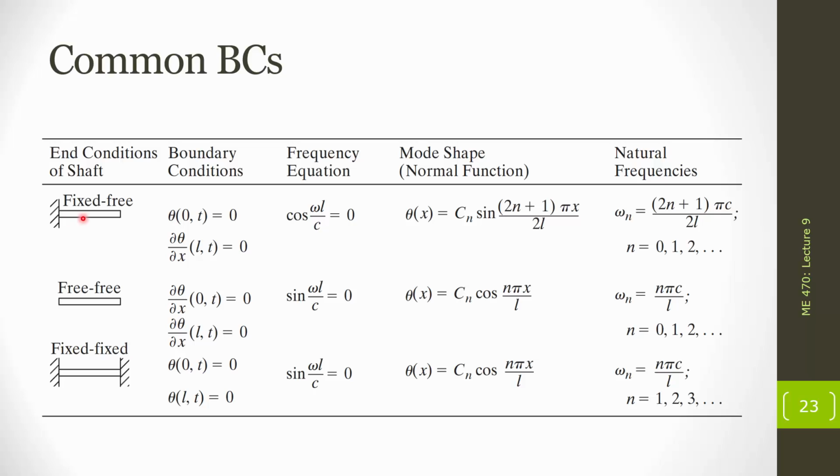And we also know that at the free end, at L, we can have no axial strain. It's a free end. It cannot be in strain. So those would be those two boundary conditions. And as we apply them in solving for that U of x, we're going to be able to find our natural frequencies and the mode shapes, which would also be our eigenfunctions.